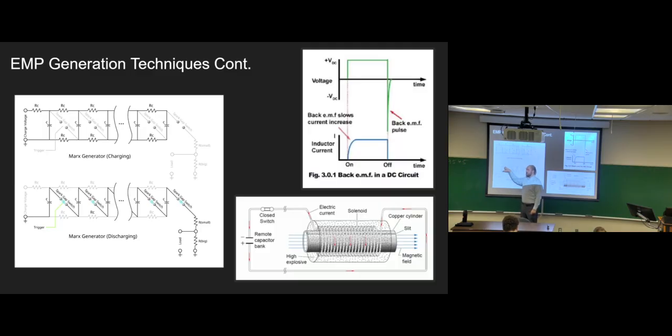So if you did inductors here, it would charge faster because the resistance is lower, thereby the capacitor time constant is lower. But when the spark gaps close, it would not change its parameters too much. It would still get bypassed by the spark gap because it's far lower resistance of a channel than the inductor would be. And also, as you said, the inductor would resist a change. But I see what you're trying to get at.